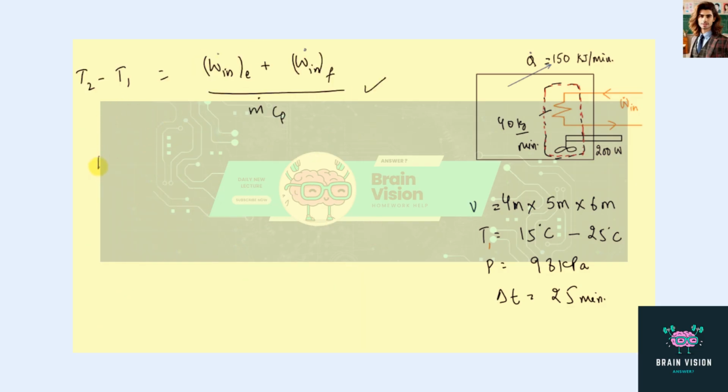So T2 minus T1, that we have to calculate, is equal to the work input by the electric heater that we have calculated as 3.151 kilowatt, plus the work input by the fan, we have 200 watts, that means 0.2 kilowatt, divided by m dot.